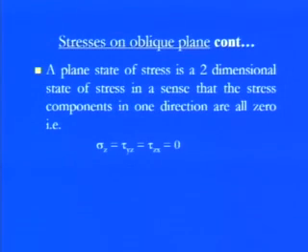So this 2-dimensional plane stress is always calculated for these 2 directions, and that is why it is known as plane stress. For the xy plane, yz plane, or xz plane, one direction we are just assuming is not existing. So if we consider this case, the plane stress is only in the xy direction.